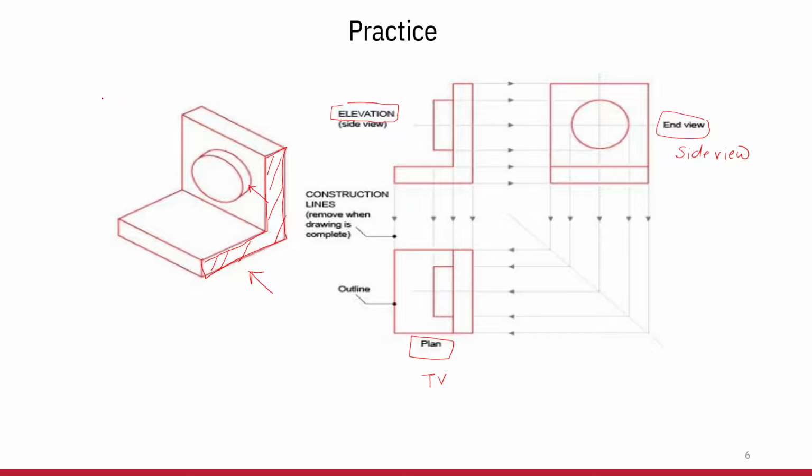Now we can easily get to know that this is the cylindrical portion, and if the direction of view of the observer is this, then the observer will be able to see the edges, right? The observer will see this curved edge as vertical, then this bottom edge will be seen as a straight line, and this curved edge will again look like this. So what does that mean? The cylinder will be observed as a rectangle whenever the observer is looking at the object in this direction.